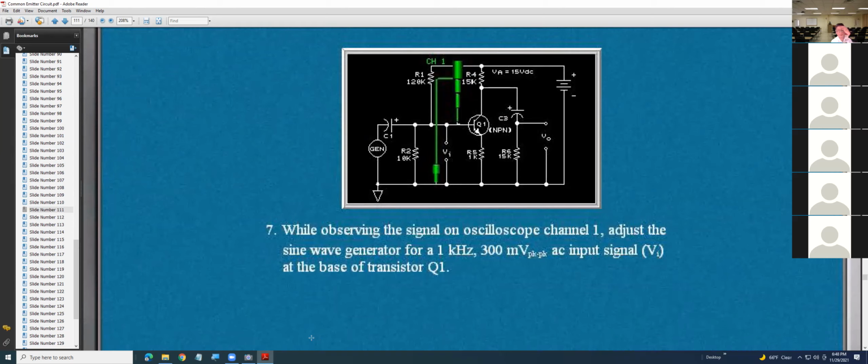It's a small voltage, so less than 300 millivolt, 100 millivolt, 50 millivolt. Then you have to connect a generator to an attenuator in the circuit board and adjust the voltage using the cursor to get the voltage you want.